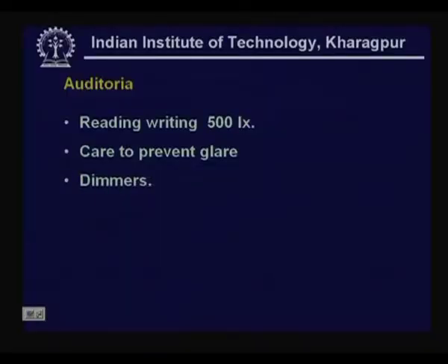There, in fact, as I was mentioning a little while ago, dimmers, as we said in a previous class, could in a simple sense be an auto transformer, because it is an AC voltage which is being used. An auto transformer is a way of producing variable AC output, and that is how these auto transformers were at one time called dimmerstats, because they were first developed for lighting applications where dimming was required.